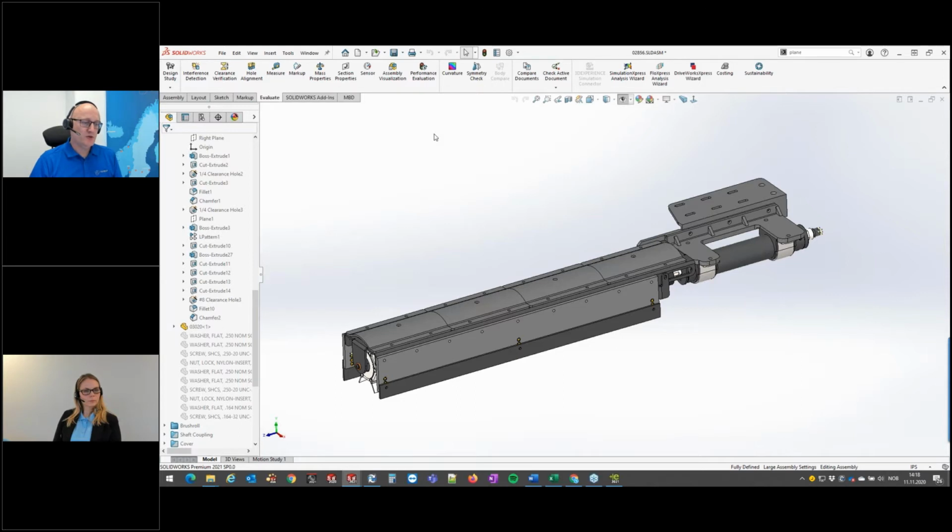It can also be used to make simplified versions of geometry, so that the assembly that contains the geometry is performing better. The new thing about the feature in 2021 is, I think, actually quite a huge improvement: you can now make the defeatured version of the file its own configuration within the same file.